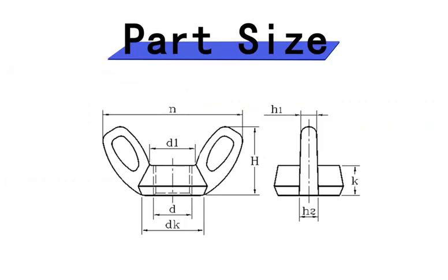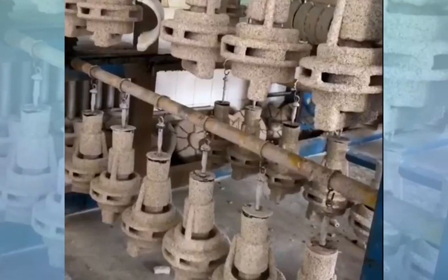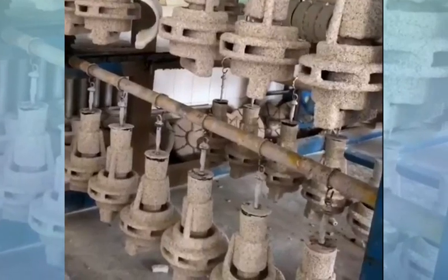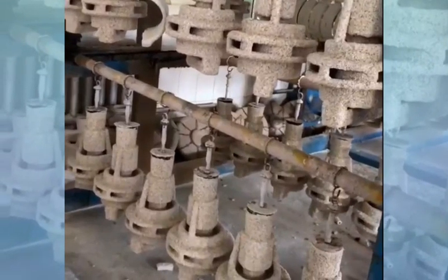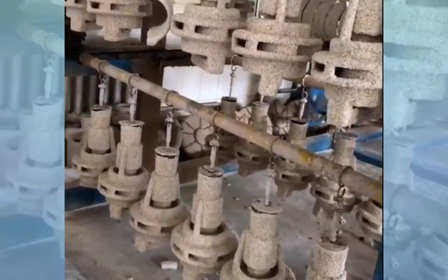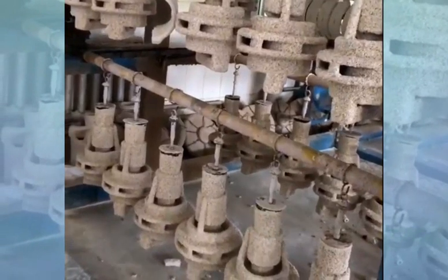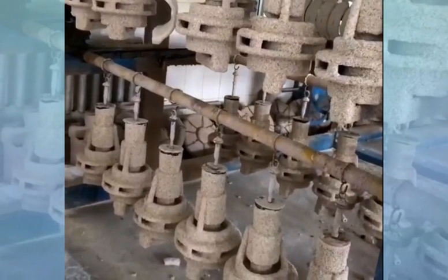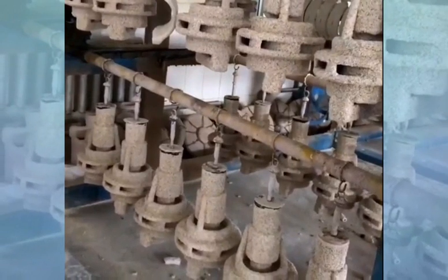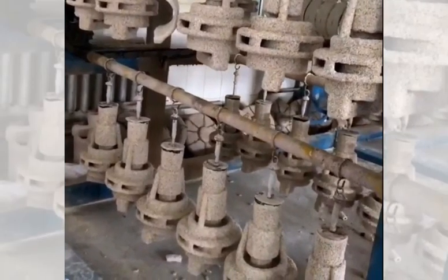Part size. Investment casting has size limitations due to the need to safely attach the wax model to the spool and repeatedly dip it in the ceramic slurry. In contrast, die casting has fewer size limitations and can create larger components, but it incurs higher tooling and unit costs for larger products. The die-cast part's size is limited by the clamping force that casting equipment can create.